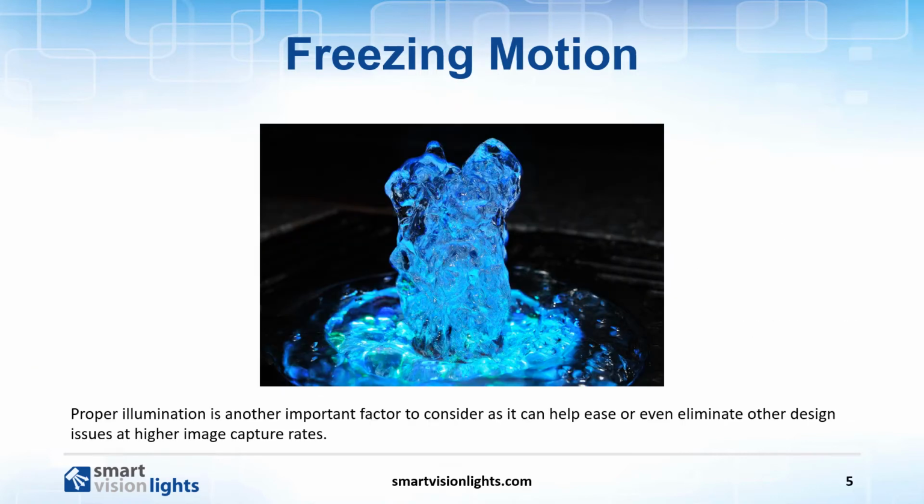Proper illumination, however, is another term more easily defined within the context of an application. It requires more than simply applying enough illumination at the correct wavelength or angle. As shutter speed increases, the target needs to be more brightly illuminated to ensure proper exposure at each pixel. Given the limited number of ways a camera system can be tweaked to gather more light during short exposure times, it is advantageous to pulse the light source to illuminate objects of interest more intensely.